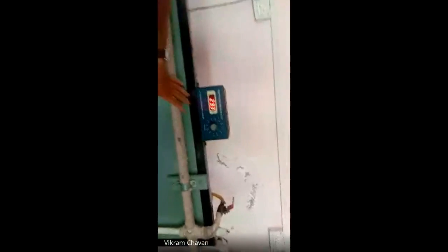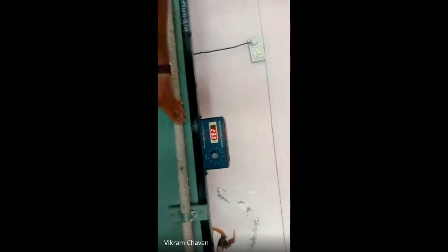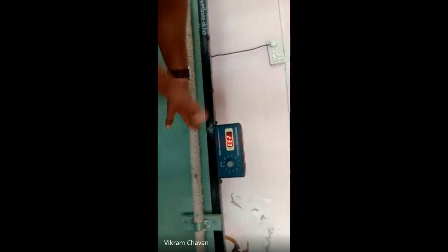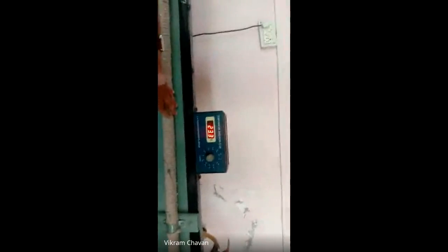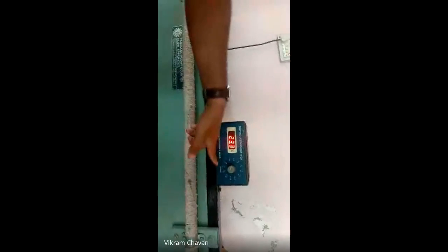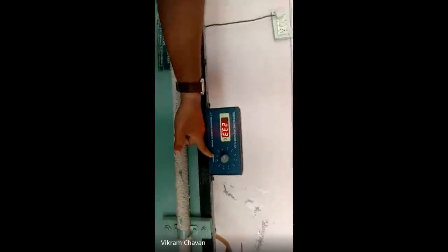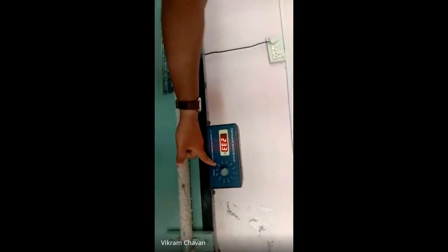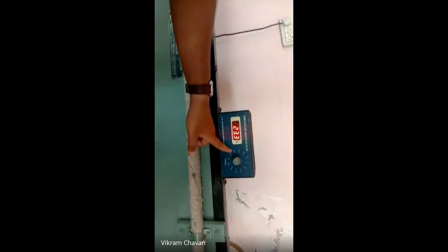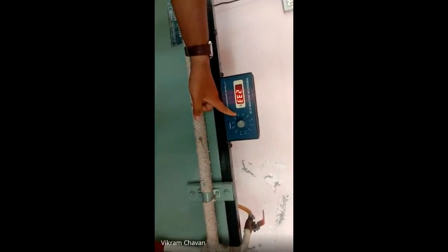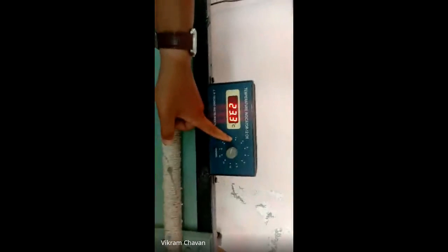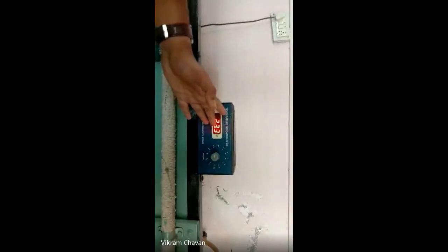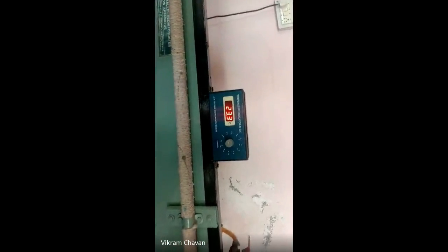Getting everyone? Okay, so T5 we will not take for the parallel flow arrangement. It is the exit temperature for cold fluid when we have made the arrangement for counter flow heat exchanger. So first four readings we have taken as T1 as hot fluid inlet temperature, T2 as hot fluid outlet temperature, T3 as cold fluid inlet temperature, and T4 as cold fluid outlet temperature. These four readings we require for the calculation of parallel flow arrangement.